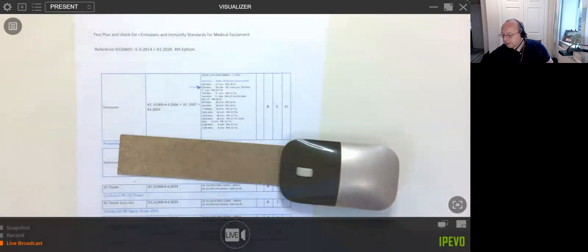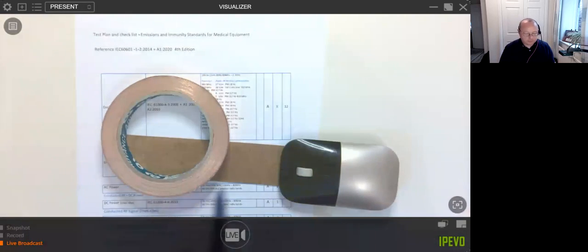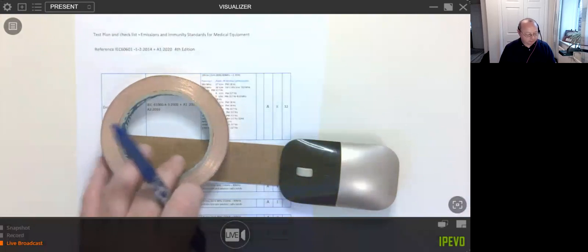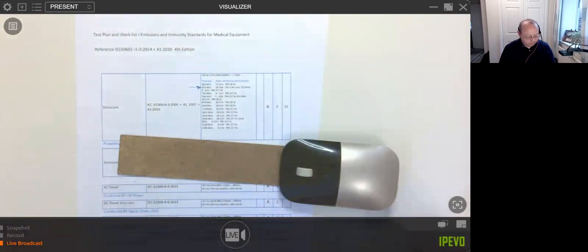How did I fix it for EMC? I've got some here, very handy. I've got some copper tape. I put some tape on it, connected it to ground, so the Flexi Track had a proper ground. And back in the chamber, at 450 megahertz, absolutely fine. So getting the design right, it might work perfectly for, say, your laptop, and you think brilliant, but the fact is, when you go to medical, it's a whole new ball game. So that's one part.